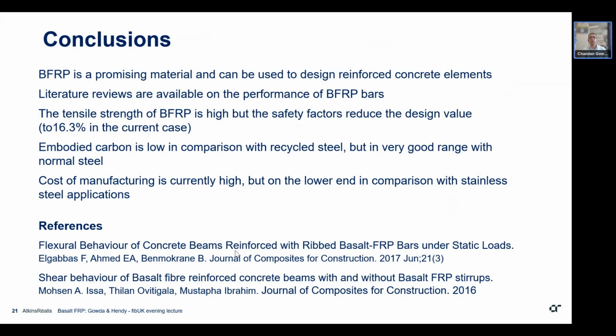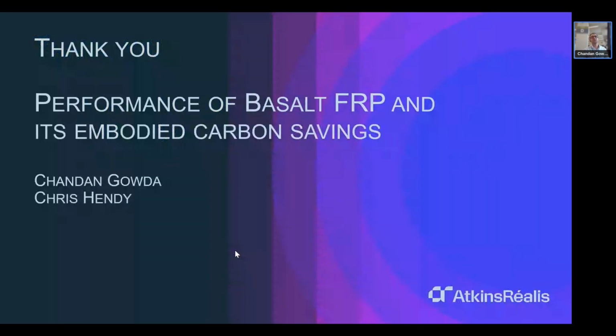The embodied carbon is low in comparison with recycled steel, but it is in a very good range with respect to normal steel, at least in the current market, in comparison with the steel reinforced elements, and at least in the case of stainless steel applications, this is a very good alternative solution at this point. Again, the cost of manufacturing is currently high, but higher manufacturing, higher consumption, higher usage will lead towards lower cost, more applications. A few references which I've used, and thank you very much for listening.